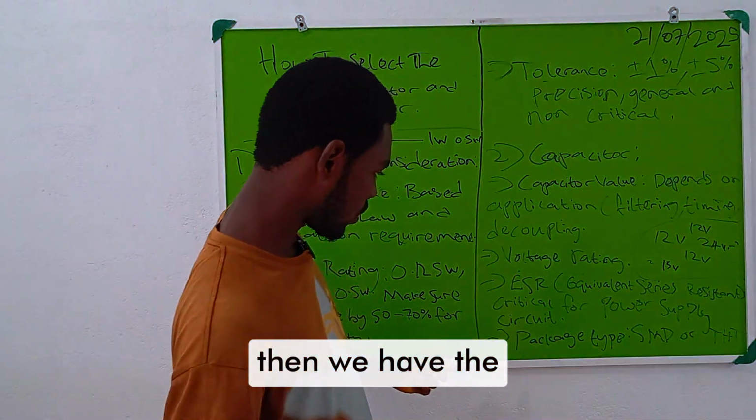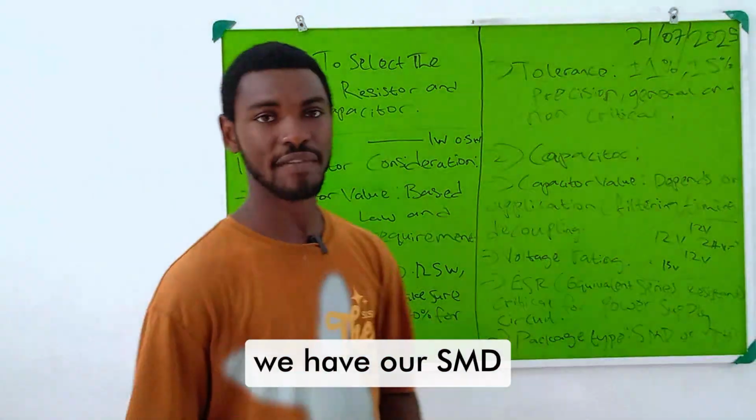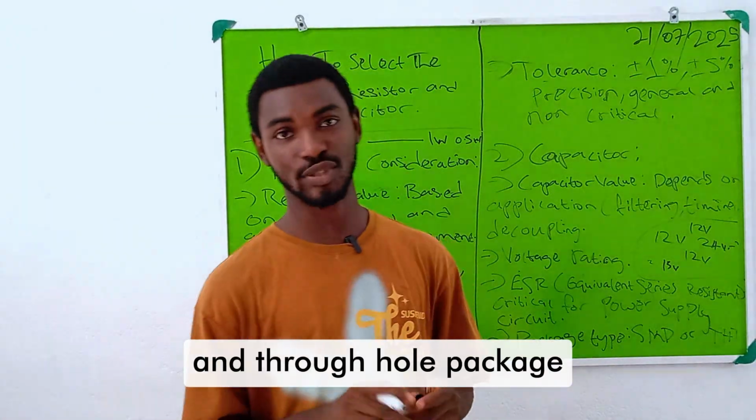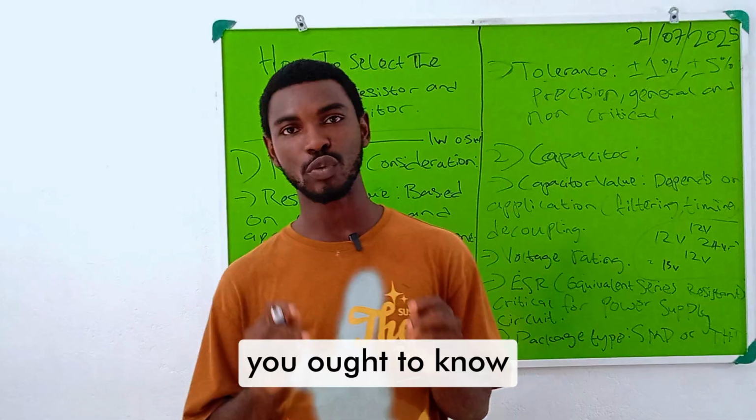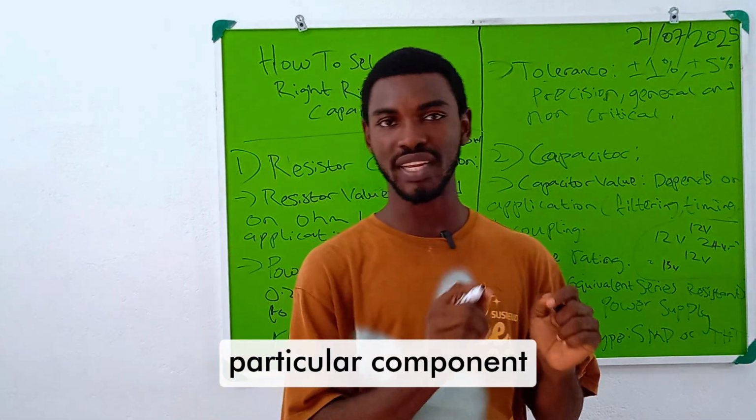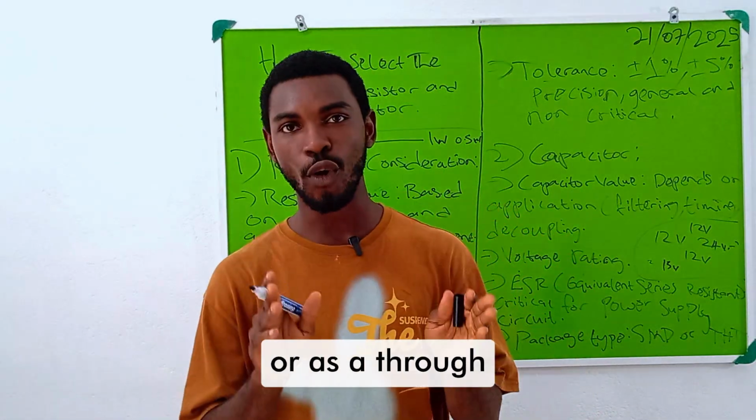Then the last one is package type. We have our SMD and through-hole packages. When designing your circuit, you ought to know if you'll use that particular component as an SMD component or as a through-hole component.